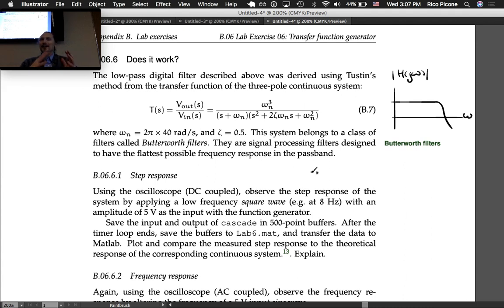pretty easily. You could draw up a circuit, find its transfer function, and build the circuit in analog discrete elements, put in an input value, measure the output value, and then take that same input value and run it through the myRIO, and it'll give you essentially the same output value, or very close to the same output value that the real circuit does.